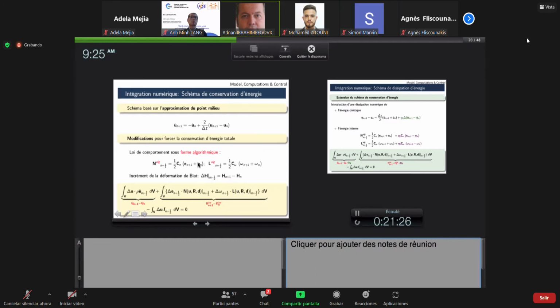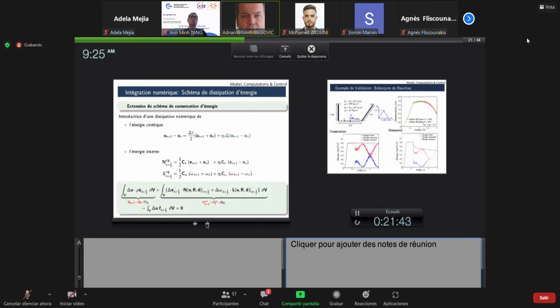So these two are not the same. This is the so-called algorithmic constraint equation. They're precisely designed so the energy gets conserved. In other words, if you suppress external loading by using this type of algorithmic computation for your internal forces in a 3D solid, you're going to make sure that energy at n and energy at n plus 1 will be the same. And that actually would keep stability of computation for very long term.